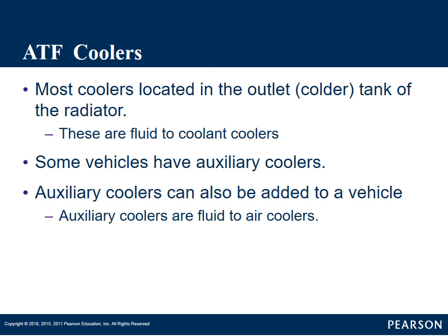Auxiliary coolers are most of the time mounted in front of the condenser. What you have is your radiator, then in front of that, if you have air conditioning, you have a condenser in front of that. Then in front of that, if they have an auxiliary cooler for the transmission, they'll mount the auxiliary cooler in front of that. The idea is they want the air passing over that first, and we'll talk about construction of auxiliary coolers here in a minute. That air flows over that cooler and removes the heat from the transmission fluid.